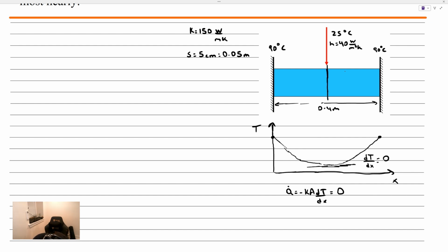If we cut it in half and we did that, we double the heat transfer rate here. It's as if we had two fins, both with adiabatic tips. So what our plan is going to be is to find that adiabatic fin tip equation, and we're going to double the heat transfer rate. So I'm going to put a 2 here automatically, and we're going to compile the formula from the FE reference manual.